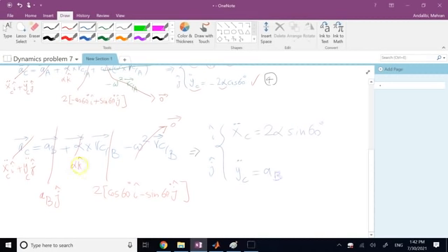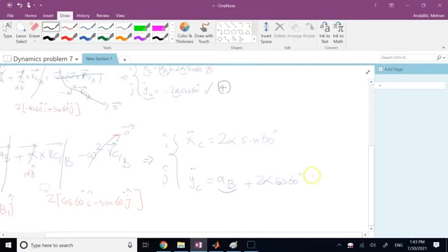And then I have k cross i, which is j, so I will get plus 2 alpha cosine of 60 degrees. And again, if you look at the bottom equation here, it introduces another unknown a of b, which I don't know. So I'm not going to use this equation, and I only use the top equation, which relates 2 of the already existing unknowns together. So this one I call equation number 5.